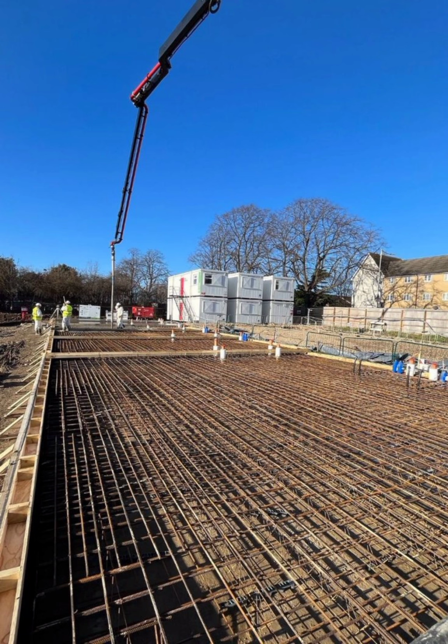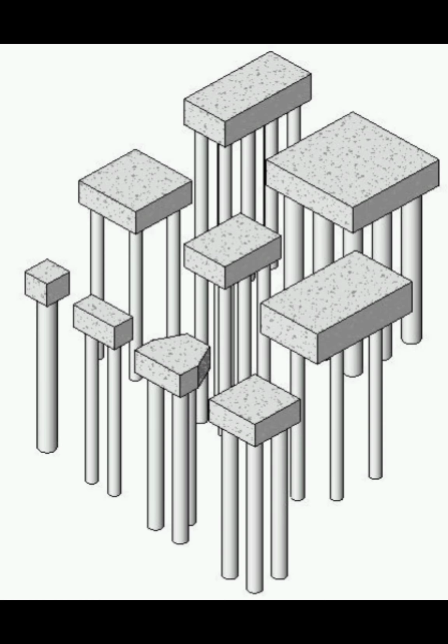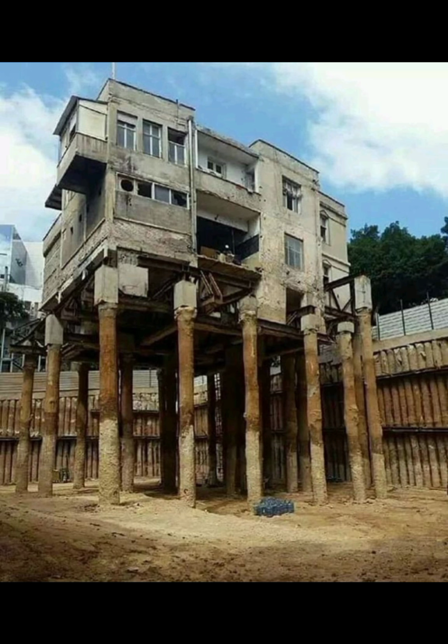The next on our list is the pile foundation. The pile foundation consists of a long, slender column that is driven deep into the ground to reach a soil or a rocky layer. So it is used for heavy structures and in areas where we have weak surface soil. It is mainly used for bridges, tall buildings, and offshore structures.